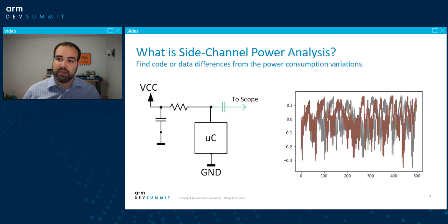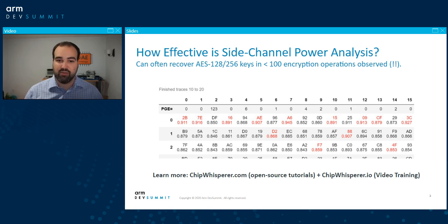Password checks are really obvious, but RSA can be frequently broken in a similar manner. Even pretty recent implementations of it can be vulnerable to this. Even more powerfully, differential power analysis uses minute differences in the actual power being related to the data processed. So even if it's the same operation with different data, if you put a number of ones over a data bus versus a number of zeros, it actually has a measurable amount of power difference. And so you can play with all that if you're curious. If you don't believe me, our ChipWhisperer project has a number of recorded traces. And again, it's open source, so you can go do that right now if you want.